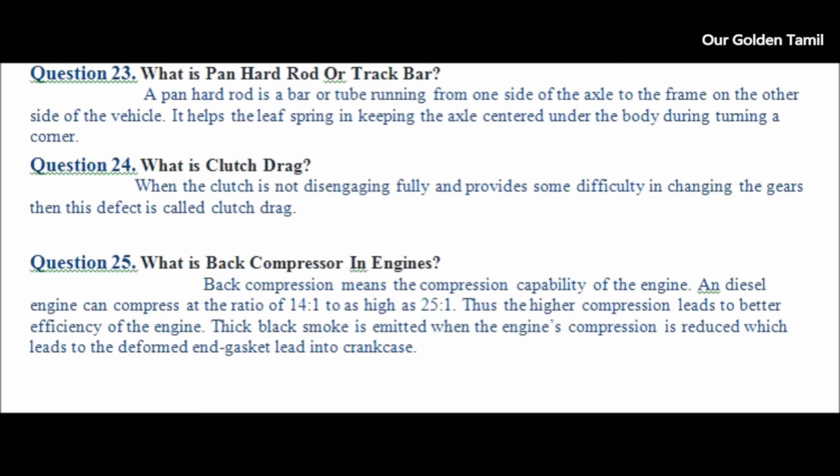Question 24. What is clutch drag? Answer. When the clutch is not disengaging fully and provides some difficulty in changing the gears, then this defect is called clutch drag.